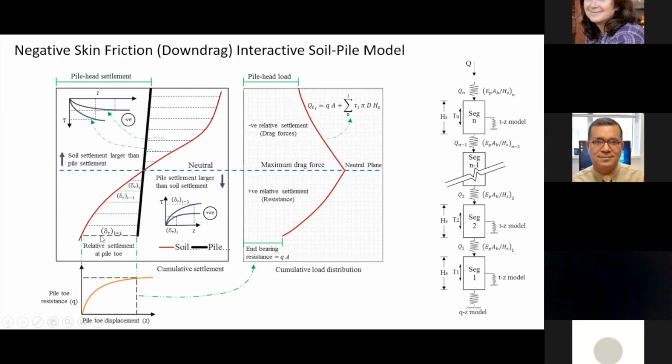It's measuring horizontal here. Okay, so that's why I see it inclined. We start comparing for each pile segment. We see how much settlement this pile segment in that particular solution is suffering compared to the soil settlement. If the soil settlement, which we calculated already earlier, is larger than the pile settlement, I'm going to have negative skin friction. You go to the TZ curve here, based on the settlement, you can get the negative skin friction on the pile, and so on.